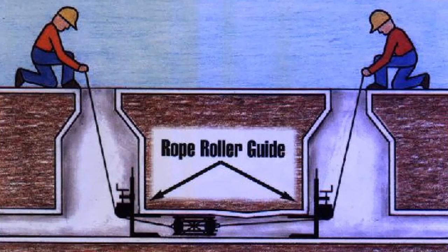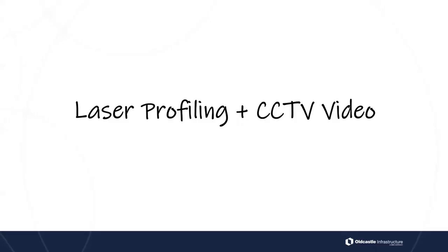On smaller diameters, on large diameters, you can go in and just spot measure every so often and make sure that the deflection meets the minimum requirements there. Now, something that's new to deflection testing is laser profiling. So this is something that is being done in other places in the country. I haven't seen it much in Utah and Idaho.